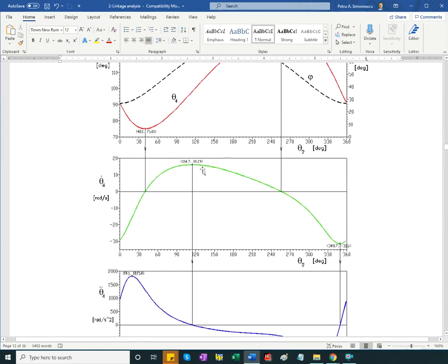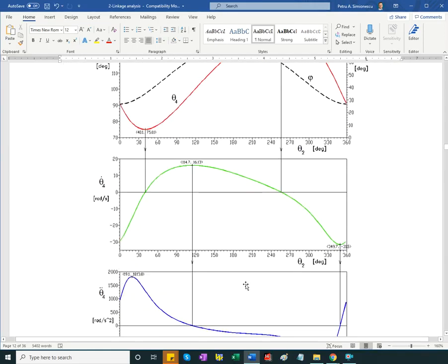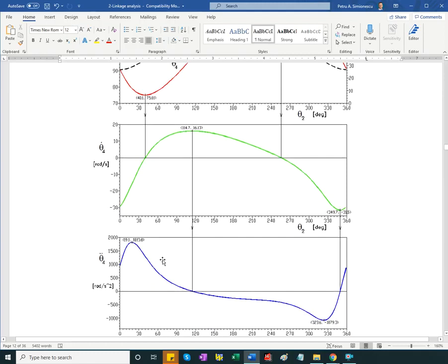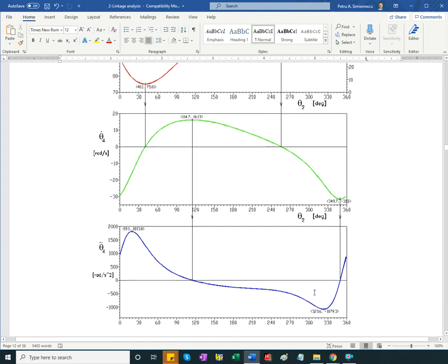That's expected, and it's one way of verifying, as you will for your project, by hand deriving the displacement, velocity and acceleration equations for the slider crank used as a punch press. The immediate way of checking their correctness is to look at the graphs and recognize they follow this rule: the velocity goes to 0 at the limit positions, and where I have minimum or maximum velocity, I have 0 acceleration.